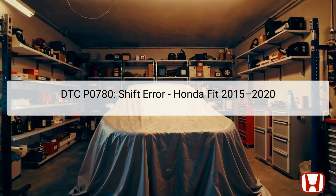The diagnostic trouble code DTC P0780 indicates a shift error within the continuously variable transmission, CVT, of the Honda Fit model from 2015 to 2020. This error is essentially a problem in the transmission's shift control system, which hinders the vehicle's ability to shift gears smoothly and efficiently. The detection of this code generally occurs when other related codes, such as P1898 and P1899, are present, indicating issues with the CVT drive and driven pulley pressure control valves.